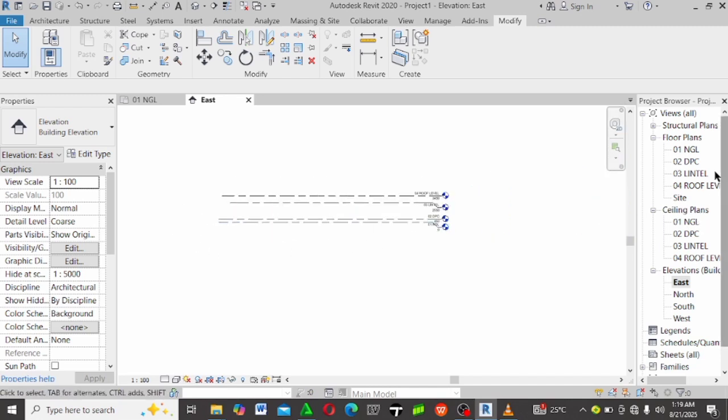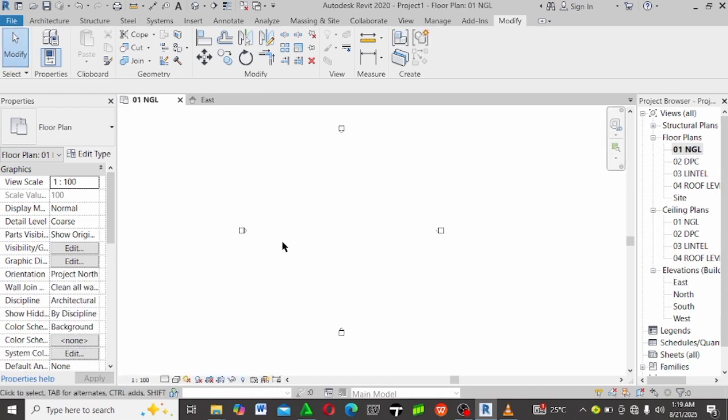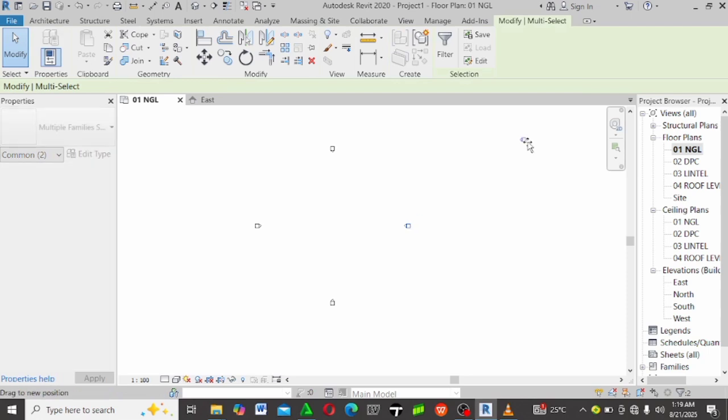You got it? So let's just go to this elevation. All these little buttons you are seeing here, they are just cameras. If this one is shifted, maybe around this place, and you have a building in the middle, this side elevation is not going to show in this elevation tab. Maybe you see, this is north, south, this is west, and this is east. So if I just click on this east now, this side will not show in the elevation, because we have moved the camera that's capturing that away. So I'll just undo that.